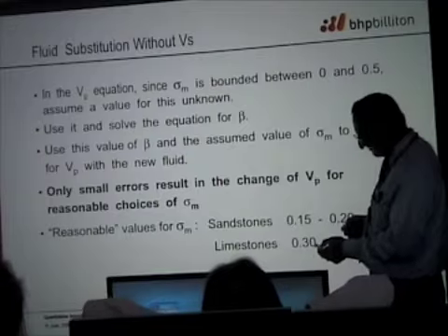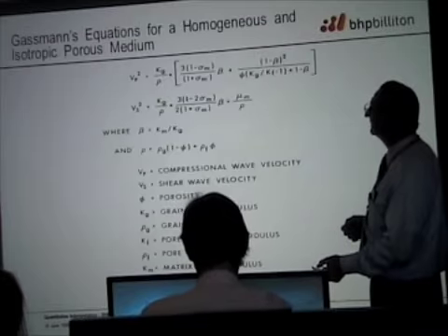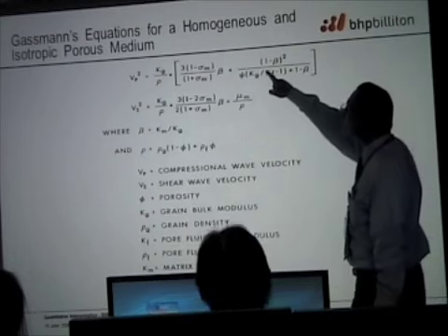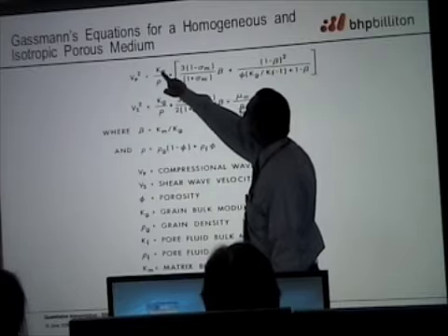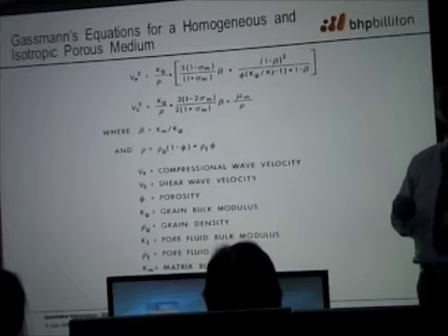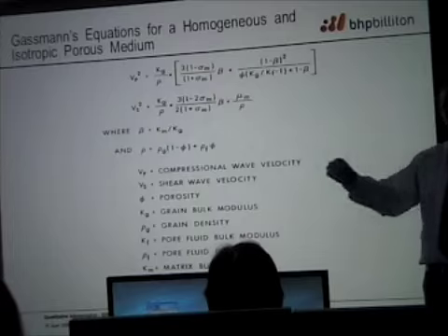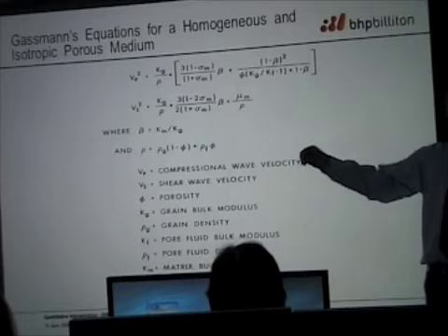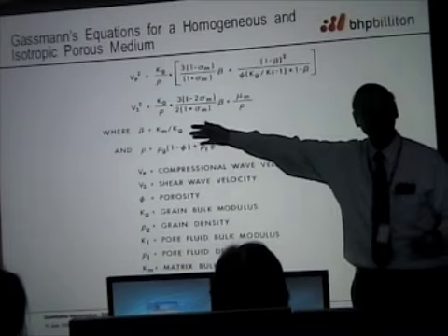And now I'm going to go back. I figured this out. And now I'm going to say something about why we chose to write this equation in terms of K and Poisson's ratio. Because Poisson's ratio is limited between 0 and 0.5, so it's relatively easy to span the whole space of possible variation. Most of the other elastic constants, you have to go from 0 to infinity. Okay?